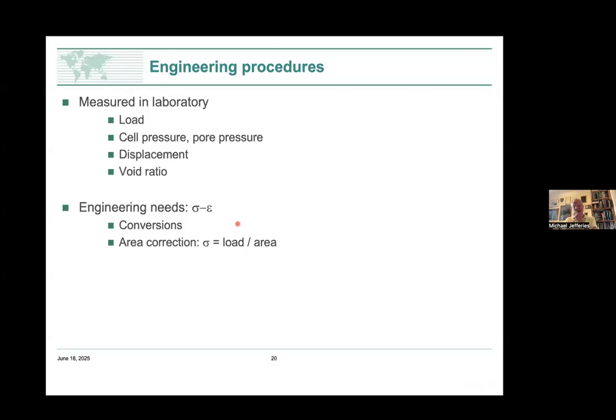And Bishop, who's one of the, shall I say, developers of the triaxial test, used to teach that the triaxial test was only reliable out to 10% strain. Well, as you know, if you look at our current literature and you go to any conference, everybody and their auntie is testing out to 20%. And that means when you look at a stress strain behavior, you can put a lot of trust up to 10%. As you go further out, you might start questioning whether the reported stress or strains are quite as accurate as they claim to be.